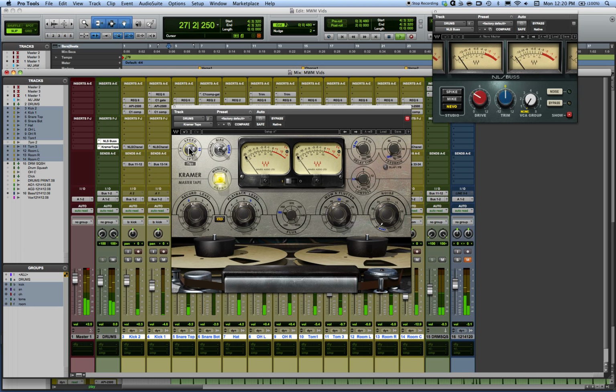So you can really hear the difference in the high end, particularly with the hi-hat. Right, so let's go with that, and then we can also go with the different bias characteristics. The overbias is going to create a warmer, richer kind of sound, where the nominal bias, which is sort of an even leveled bias, it's not saturating the tape, will actually give a little bit more rich high end. So you really hear the openness of the drum kit and the warmth of the overbias.